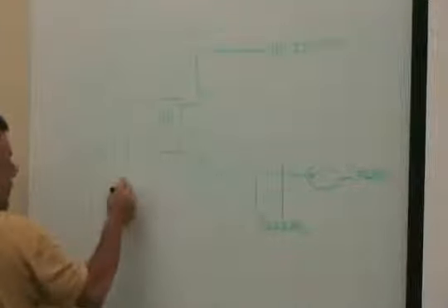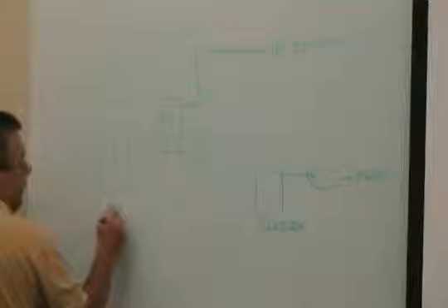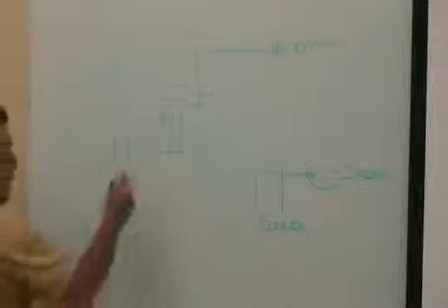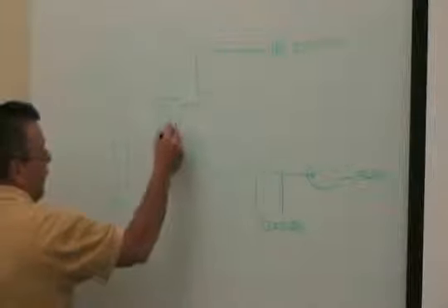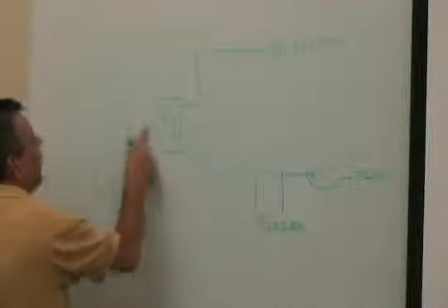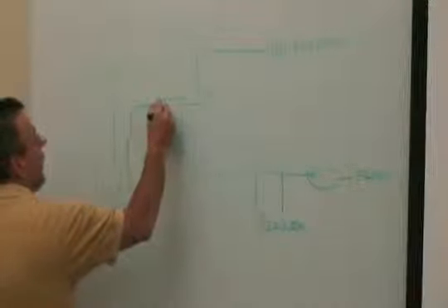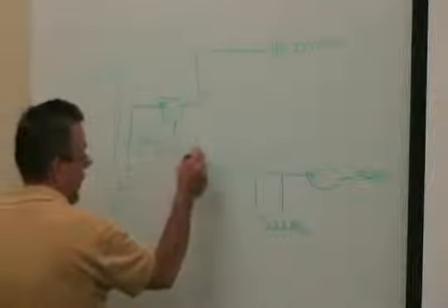This is cold. I've got to introduce another pump. So I'm producing 85-degree water here with my cooling tower, and 95-degree water here. The water's going like this. Actually, that would be counterflow operation. These would be backwards. 85 here. 95 here. But I can get a 5-degree approach on that heat exchanger pretty easily, where I can produce 85. Actually, I might even be able to get that even closer.